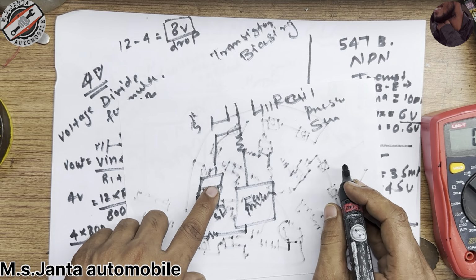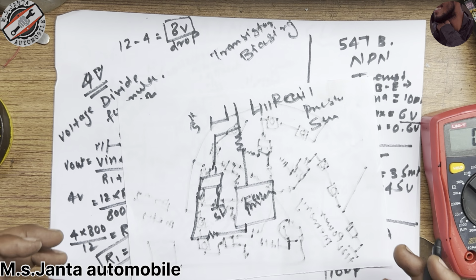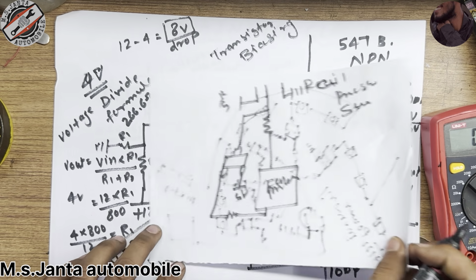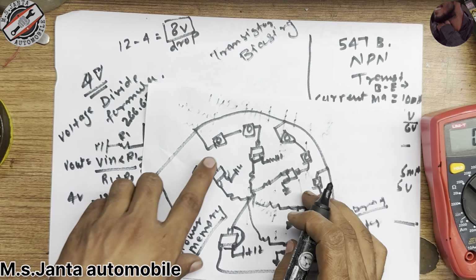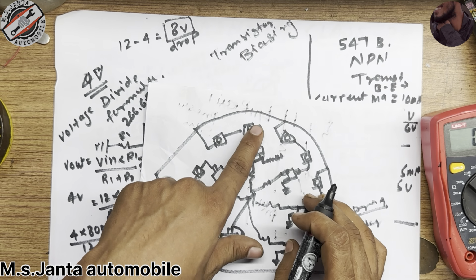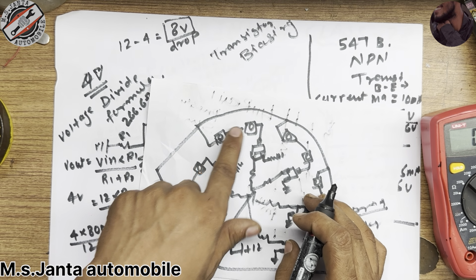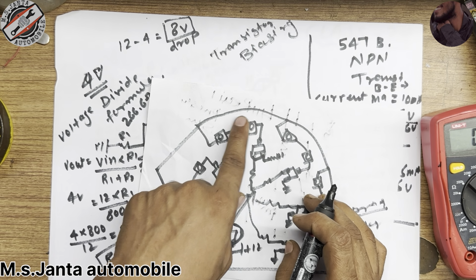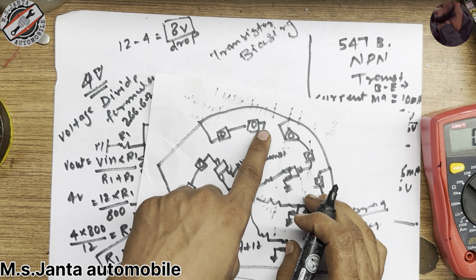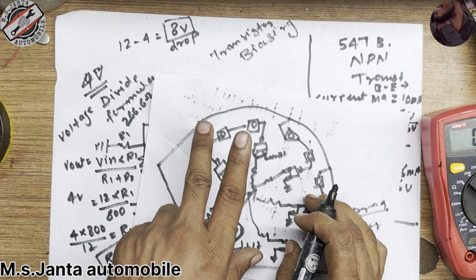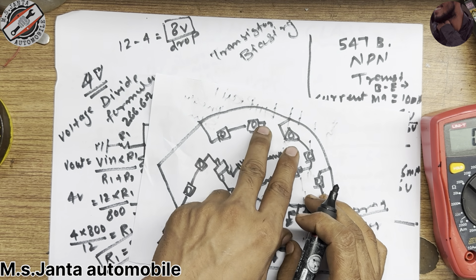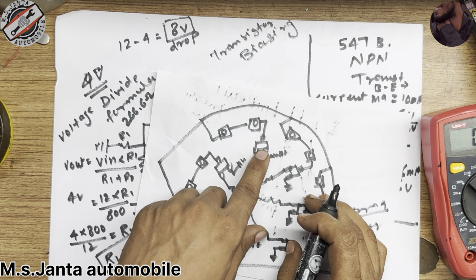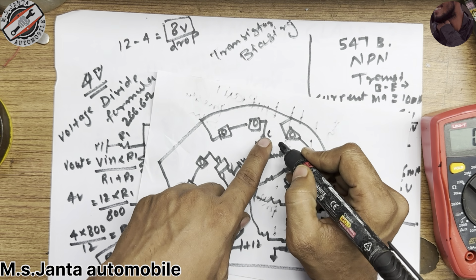So transistors are used in the ECU in many places. Okay, so you have to know how you can easily find the load. Suppose we have a load here, it is connected in series, and one side is positive. Obviously this LED needs negative and positive. If 12 volt is present, it means we need the negative. Yes, it needs negative, so it will be connected to the collector of this transistor.